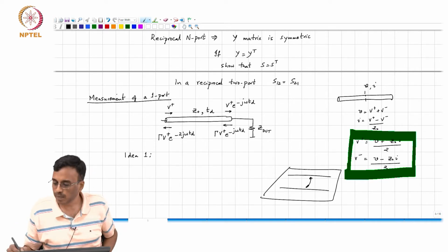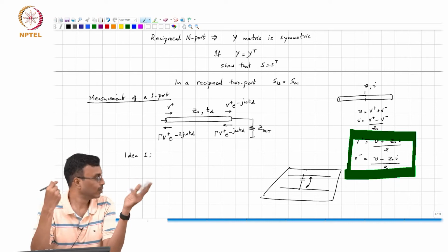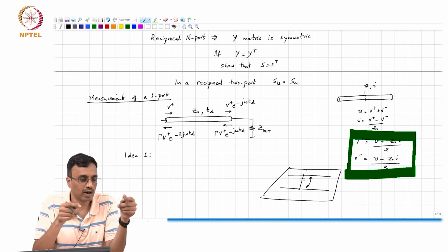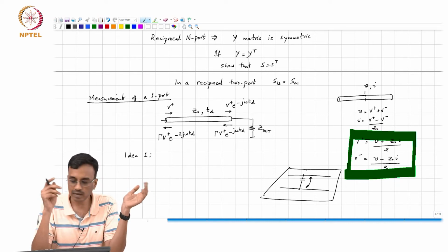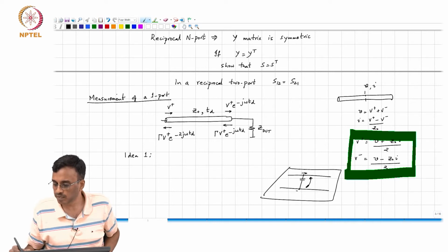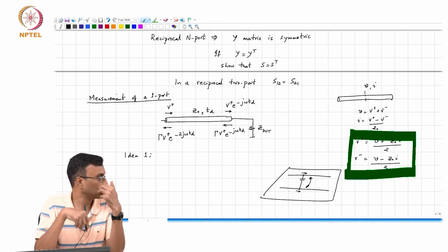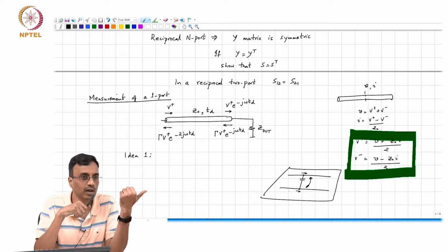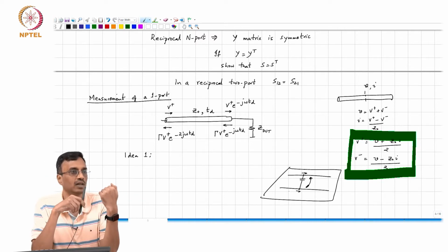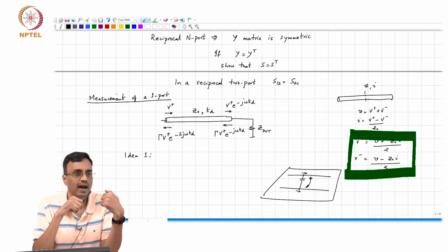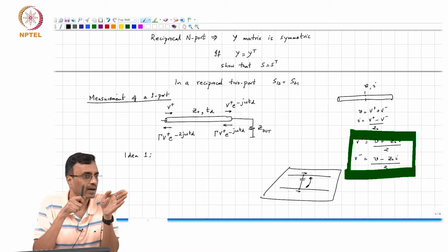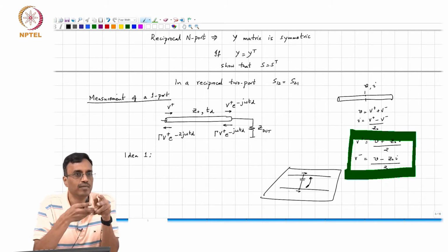There is capacitive coupling, because two conductors separated in space have some capacitance. There is also inductive coupling, because some current is induced in the second one due to the first one. So in principle it is possible to measure both current and voltage flowing on a line without physically cutting it to measure the current.